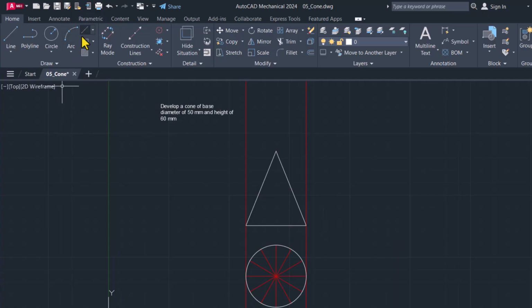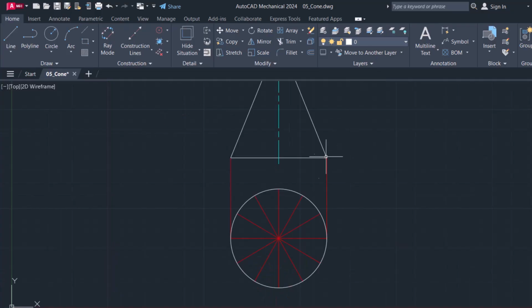And then let's come in here, click on that center line, and I want to draw a center line through here. Okay, so maybe I can TR for trim. I'll trim that portion, and then these portions as well. Okay, so let me label these.